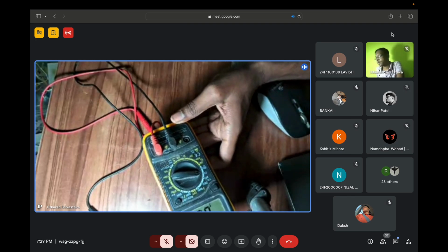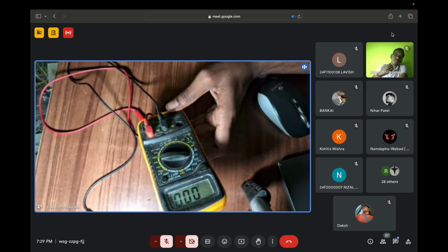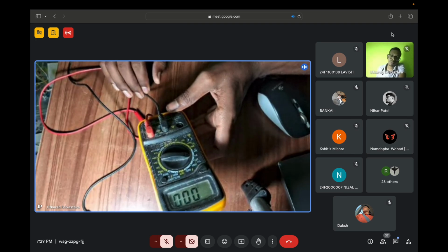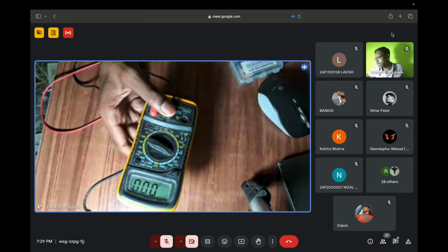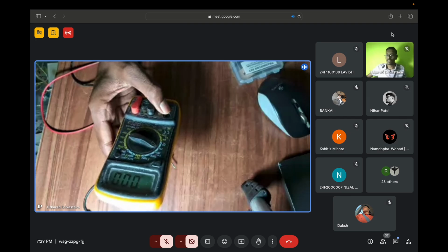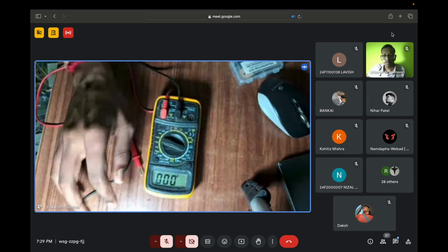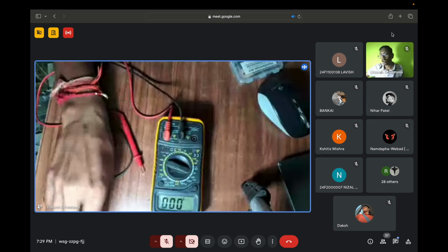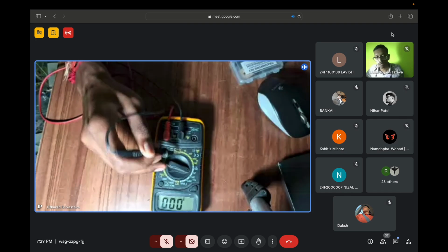Okay, so this functionality is basically used when we are measuring current which is more than like 5, 6, 7 amperes of range. Not 6, that is too high. I can say 1 ampere and 2 ampere. If you're dealing with such kind of current, again I'm telling you current, not voltage. Okay. These are different. So basically, if you want to check voltage, you can connect over here. And also, if you want to measure the resistance, you can connect your multimeter in this range.